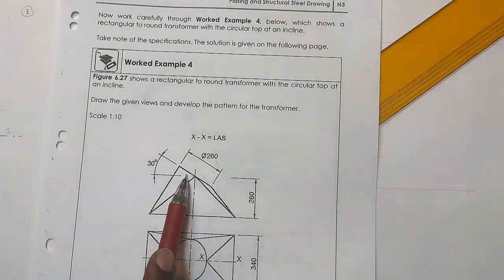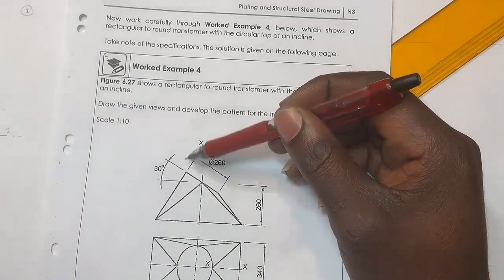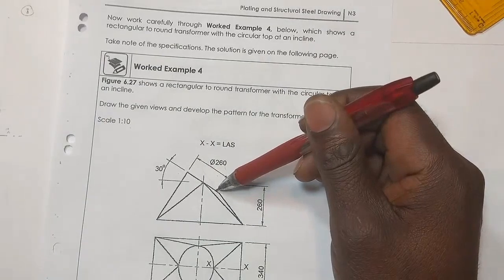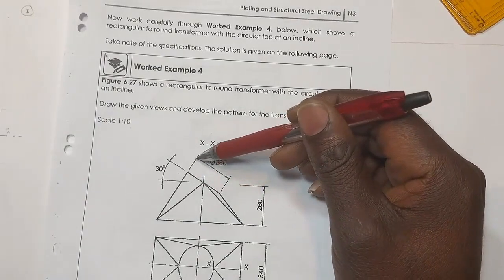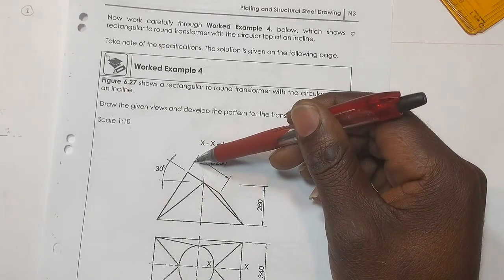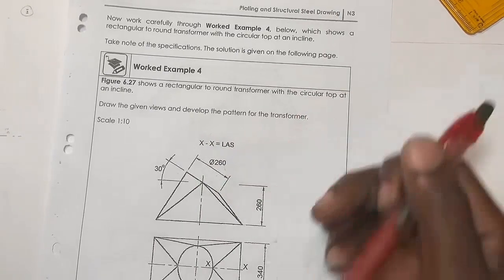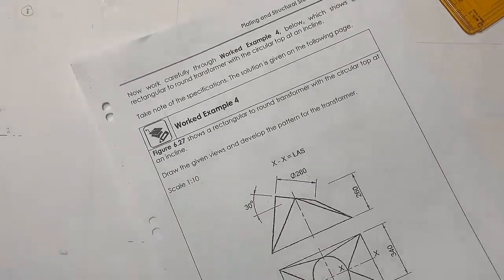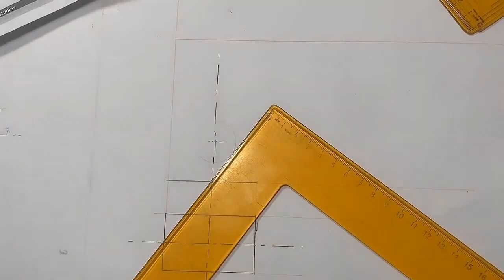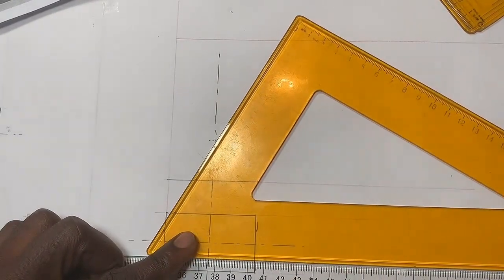It's at an inclined 30 degrees. But then if we extend this line, you see I was teaching this one, is it last week? So I extended this one and extended that one as if I'm looking for an apex point. Do you see that it gave me a point somewhere there? You understand? So if this is at an angle 30 degrees, so this one is going to be at an angle of what? If I say 90 minus 30, I'm getting 60. So which means I can draw the auxiliary of it at an angle of 60. This side. Having what?